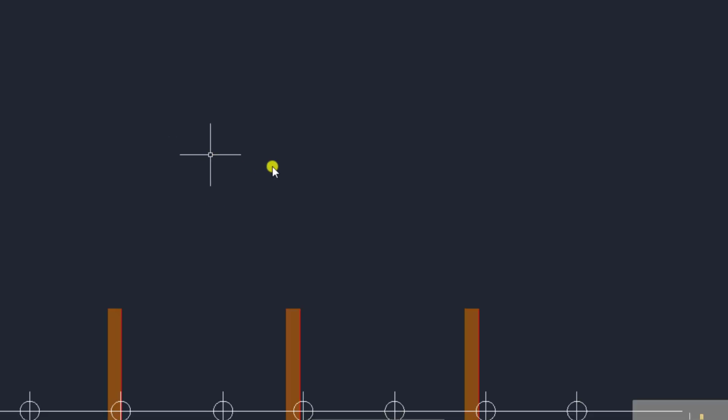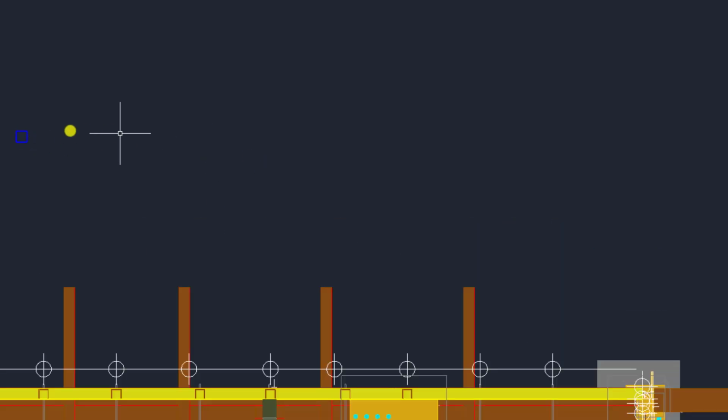Okay, let's create some bolts on this SHS. So I go to quick view, select that object, select the view direction, hit enter. View depth extension, I don't want 1000, I want, let's say, 200. And view extension along x-axis, again I want only 200, and y direction also I want only 200. And here is the view, and I go to plan view and I get this view.